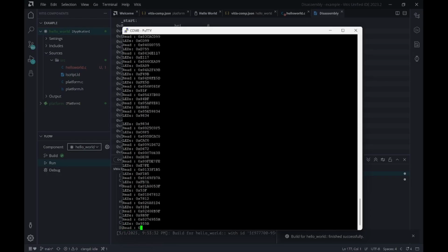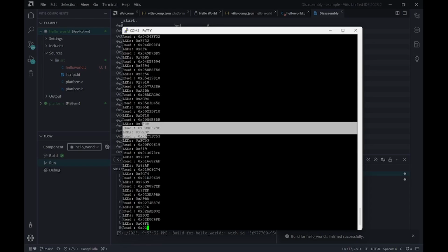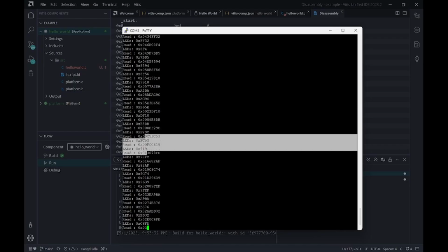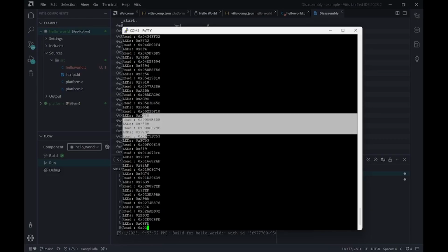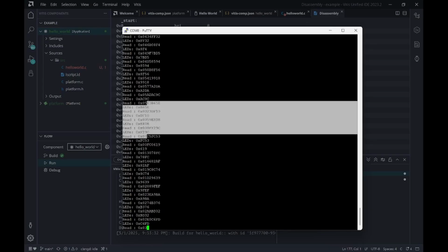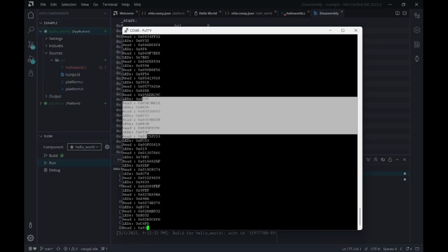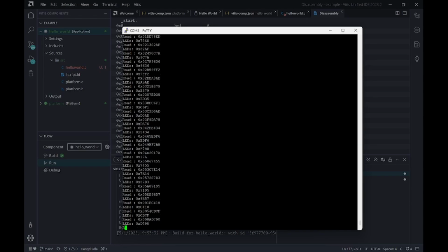I don't know if you can catch it, but once it hits around 05F is where the period marker is. So this will only loop up to 05F and then it will restart. AXI protocols take more than one clock cycle. So this 32-bit timer, because it's using AXI protocols, we can't actually track every timer tick up, not with the console, at least. The timer itself does track every clock cycle.